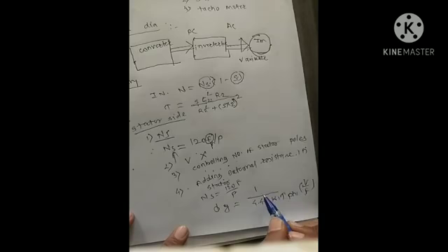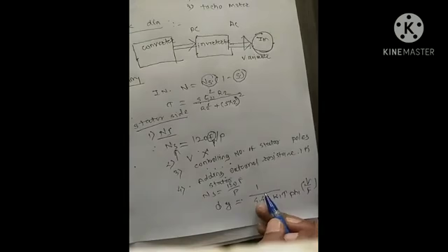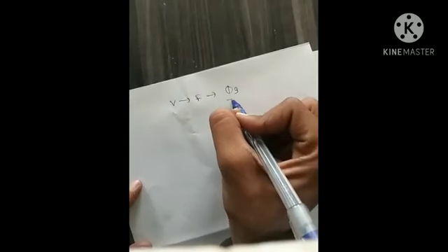If only the supply frequency changes, the phi g value is affected. If phi g increases, it causes saturation of the stator and rotor cores. Due to this, the magnetizing current also increases, and the power factor of the motor is highly affected. So if we change V, the supply voltage, along with F, then phi g is maintained constant. Hence this method is called the V by F method.